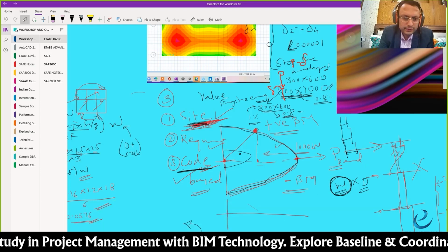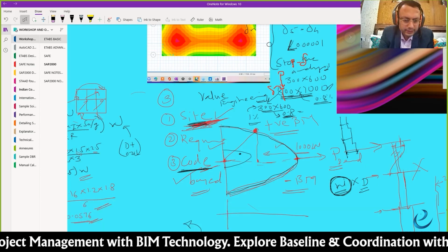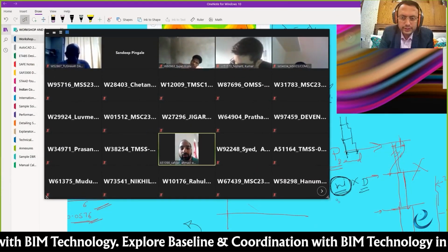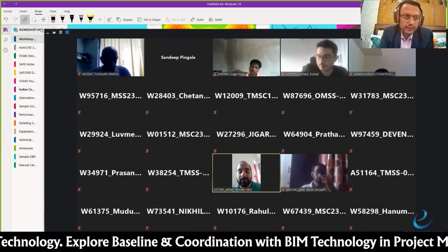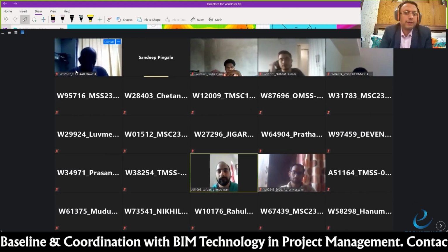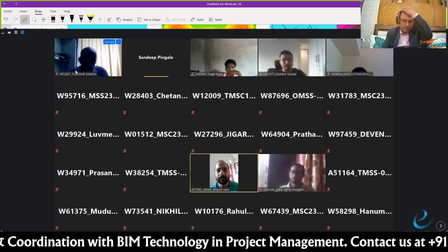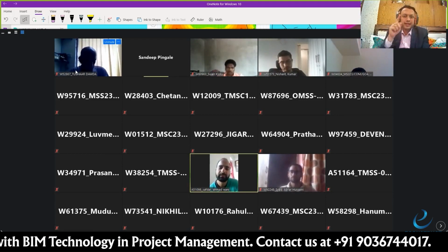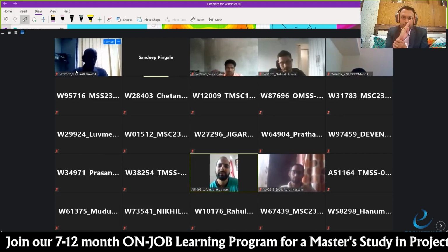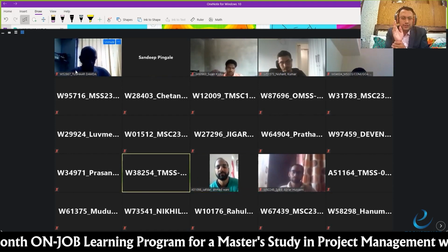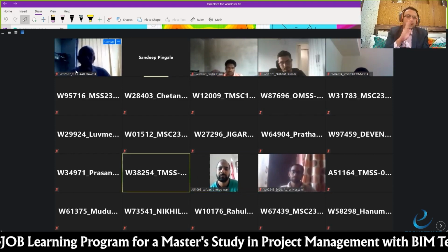Anybody? Hello, sir. Yes. Sir, is there any criteria regarding P delta, whether we should go for the P delta analysis or not? I think there is a provision in the American code. See, if the delta is 0, P delta is 0. Do you agree? If the delta means the first deflection is 0, there is no deflection. So P into delta, P into 0, is 0.